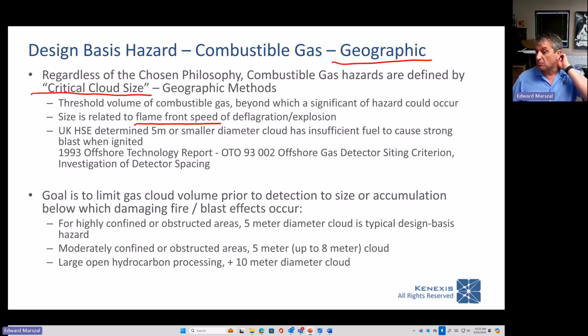So something as small as a half PSI or 1 PSI of overpressure is going to be enough to shatter glass. A 3 PSI overpressure is going to be sufficient to knock over, to damage, to collapse cinder block construction buildings. And at something like 5 to 10 PSI overpressure, any kind of normal construction is going to get leveled by that degree of overpressure.